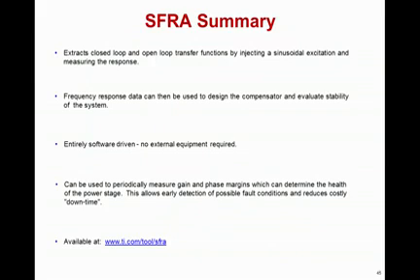Some benefits of using a software frequency response analyzer are that you can do the system frequency response measurement entirely in software. This prevents you from having to cut the control loop and insert a probe or some other measurement device. It allows you to design the compensator and measure the stability response of the system. You can use this periodically in your system to measure the health of your power stage. So in this case, you could measure the gain and phase margins of your design and monitor those over time to track and see if they are getting to a point where the control loop might become unstable.